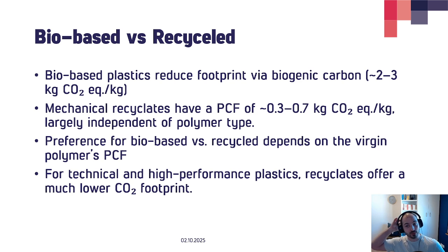So here we have the points summarized. Bio-based plastics reduce the CO2 footprint via biogenic carbon, which is around 2 to 3 kilograms of CO2, depending on the plastic. Mechanical recycling has a product carbon footprint that can be between 0.3 and 1 kilogram, but 0.7 is probably also a good estimate. And it largely is independent of the polymer because washing and sorting are independent of the polymer source, and then the extrusion is a little differentiated between the plastics.